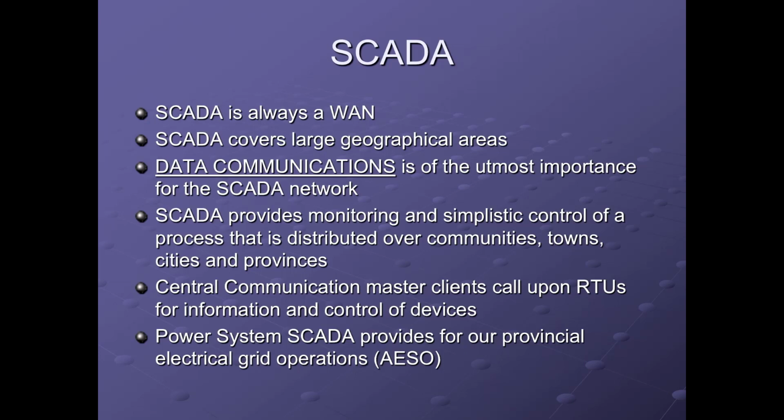And really, before SCADA networks came on the scene in wide area networks, like for electrical and gas distribution and all those things, all of this was looked after by central engineers and operators getting on the telephone and calling up these remote manned locations and talking to the site operator. They collected data as operators went around and looked at the instrumentation and recorded values and statuses, and also called in to report alarm situations or values that had exceeded thresholds. There was all this communication that occurred basically by telephone, with operators and engineers communicating that way.